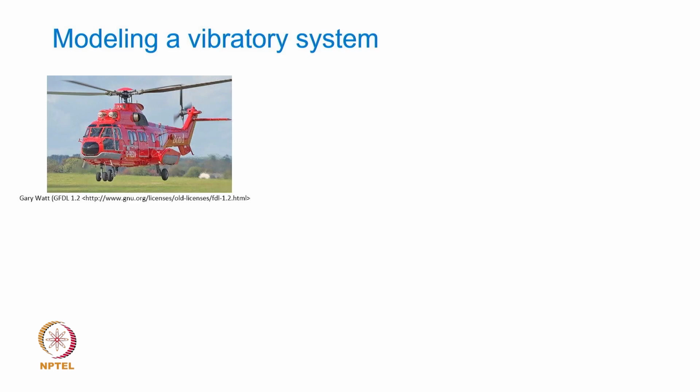Of course, this is too complex and too big a system to be modeled simply, but if we assume that as it lands on the surface, it is the landing gear that touches down first, and take a very simplistic vibratory model of this system during its touchdown process, treated like a spring mass system, then the landing gear provides a sort of compliant supporting structure for it.